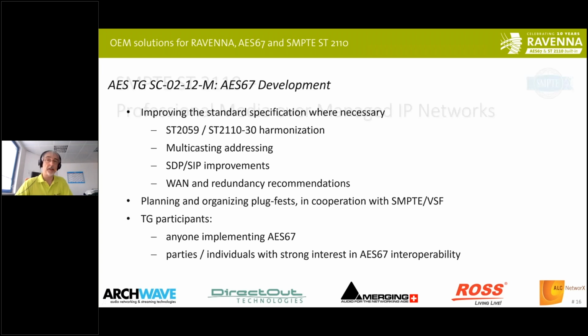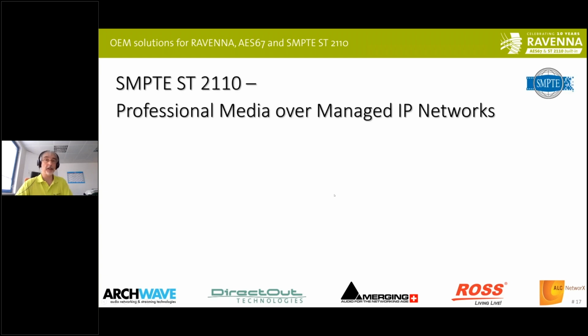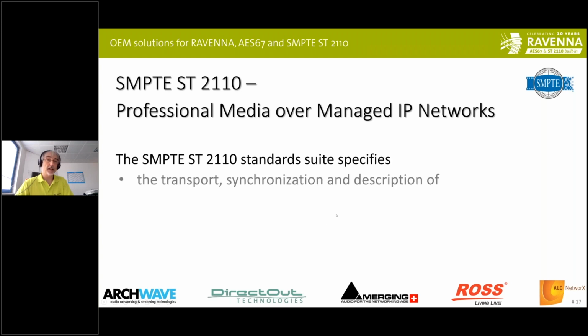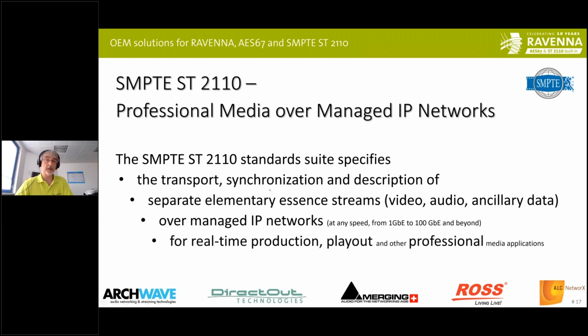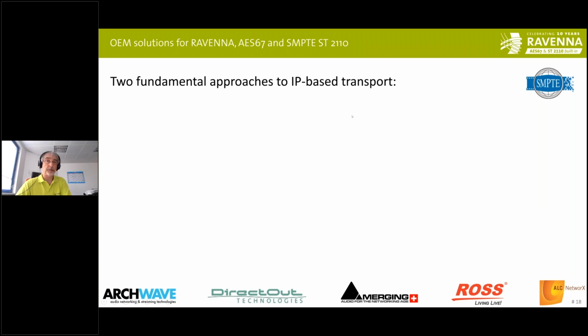All right, that's AES67, a quick look into the SMPTE ST 2110 suite of standards. The professional media over managed IP network standards is a suite of standards which specifies the transport and synchronization of separate elementary essence streams, so audio, video, and ancillary data being transported as individual separate essences on the network over managed IP networks, and the main application area is real-time production playout and other professional media applications. So there's nothing for over-the-top or internet-based transport of media essence.